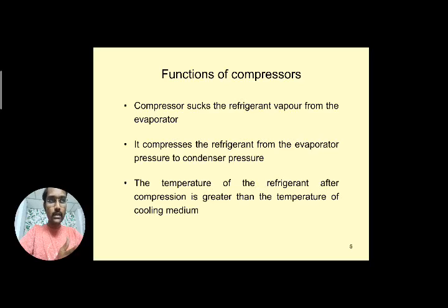And the next function of a compressor is that it will pump out, you can use that word, it sends the vapor refrigerant with very high pressure and very high temperature to the condenser component. This is the third function. First function is sucking the refrigerant from the evaporator, second function is compressing the refrigerant, third function is pumping the refrigerant to the condenser component. That is 1, 2, 3. So 3 main functions are done by the compressor. With the given pressure, the refrigerant will move into the next components, right?